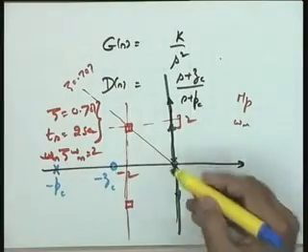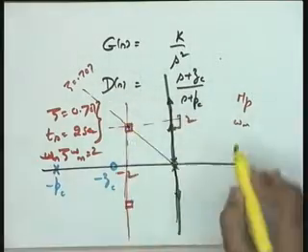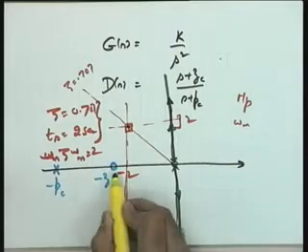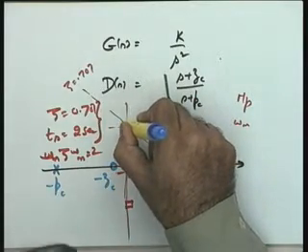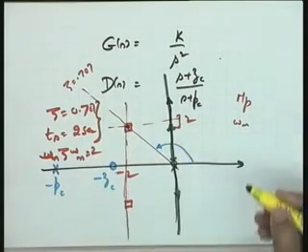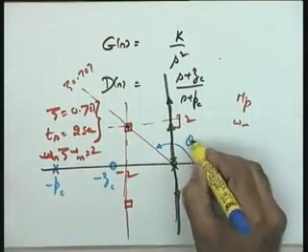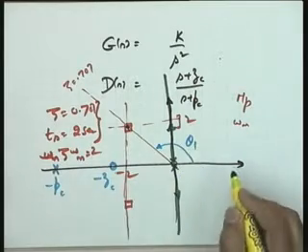Okay. Now you see that as far as this is the location, you want that the overall root locus, when the pole and the 0 have been placed, should satisfy the angle criterion at this particular point. So what is the net angle contribution by these two poles? You can calculate. Let us say this is theta 1. In that particular case 2 theta 1 is the net angle contributed.